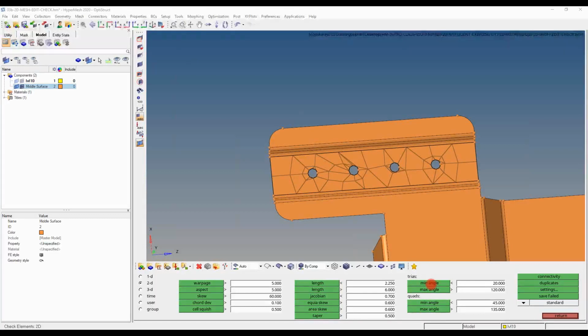And again, we're going to kind of dumb it down and think of high quality elements as generally those that match their perfect shape. For quads or squares, it's a perfect 90-degree square. For a tria element, it's looking to be a perfectly equilateral 60-degree triangle. Now, how this tool works is you set a threshold, and then you click the green panel to check for only that check.